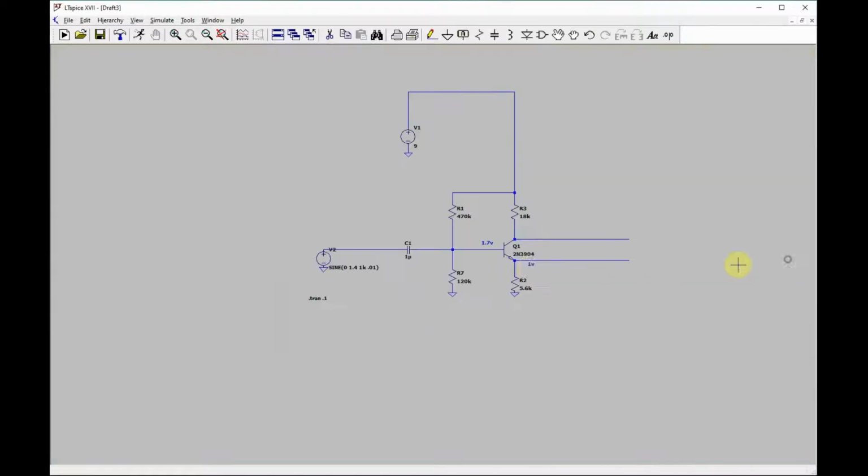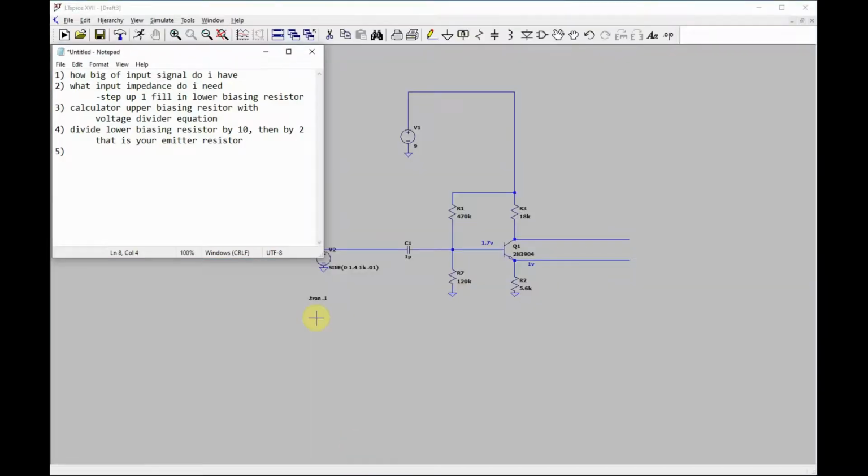So this is basically how I usually set them up. You start off with figuring out... let me put this last one in. Sorry. Okay, I will put collector resistor equals gain times the lower resistor, or let's say emitter resistor.